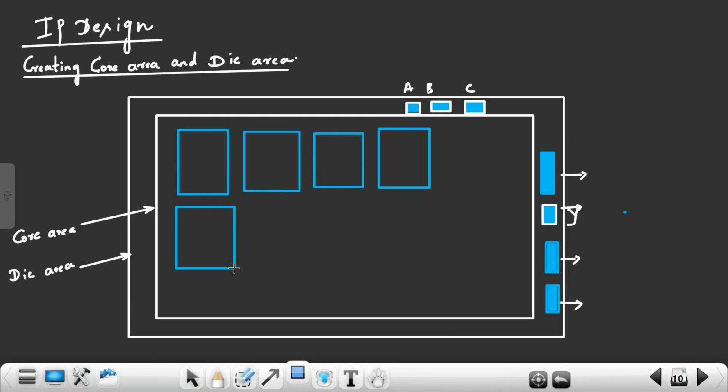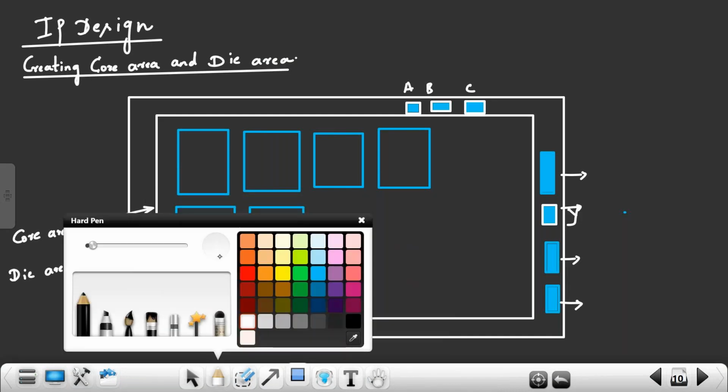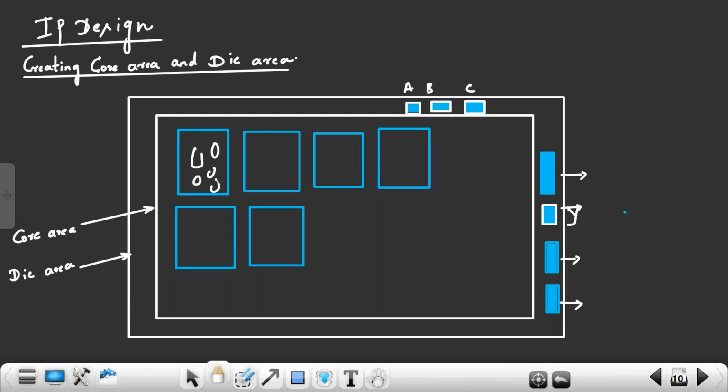I am directly placing the layout of a macro. I am not going to do physical design for these memory elements, because if I start doing physical design, each memory element will give me 10,000 cells, totally 1 lakh cells. These are small cells: small NAND gates, AND gates, everything. This is having small things.